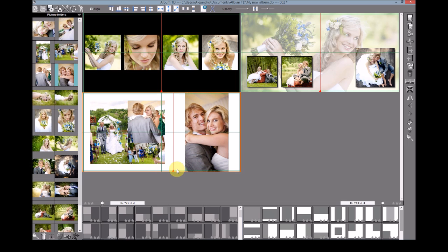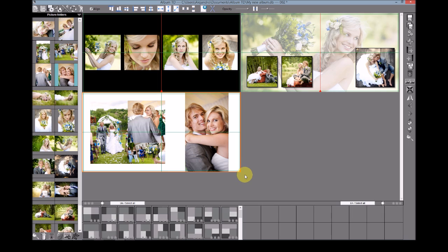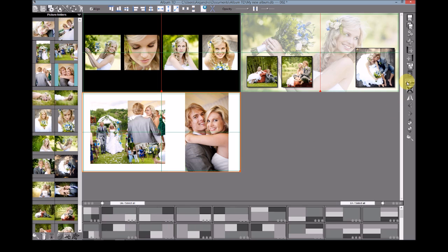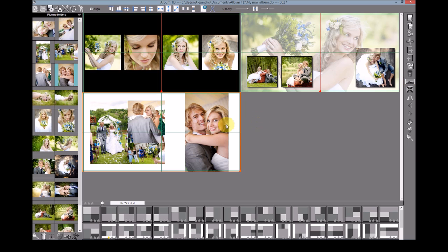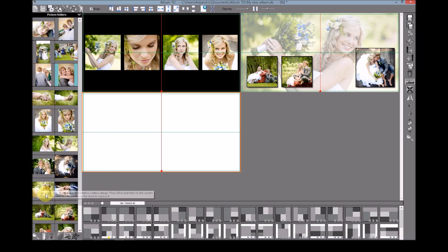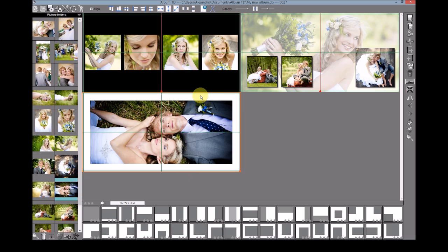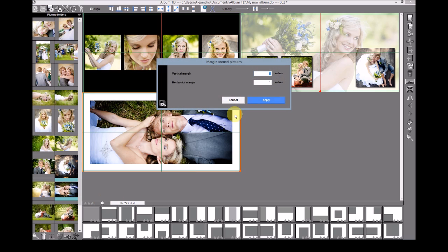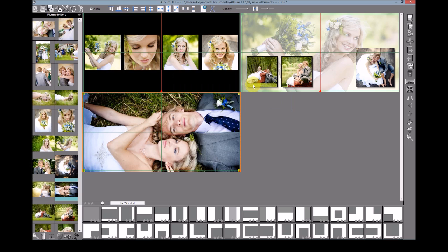And you may also design sheets in panoramical view. That means without a center. You can move the center without moving the pictures by dragging it and pressing Ctrl, or by just selecting the panoramic option here. Let's clean this sheet by pressing the X at top and drag only one picture to the sheet, and it will fill the whole sheet. We may change the margins, and now it fills the whole sheet.